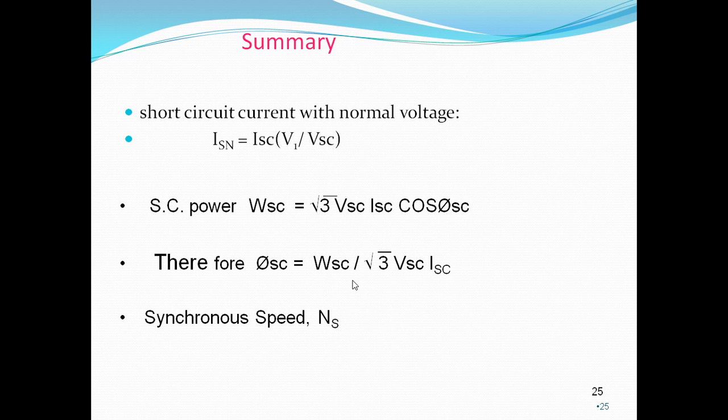In it, we apply the normal voltage and take the readings of wattmeter, ammeter, and voltmeter. From this we can calculate total resistance and total reactance of the circuit.